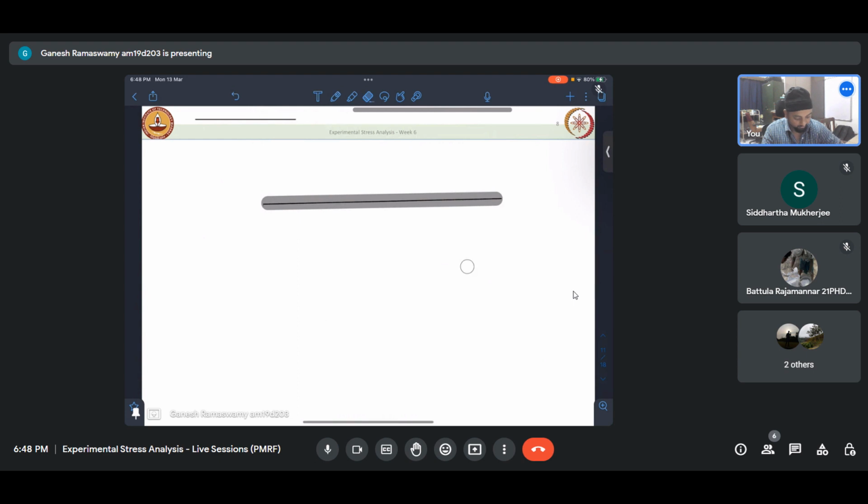So if my fringe order at that point is 1, then the fringe order at a pixel here would be some 1.1, let us say. And if it is increasing that way, then this will be, let us say, 0.9. Let the fringe gradient be from top to bottom. Now, if I were to have a pocket of pixels which basically has an if-else statement, what this is doing is we are having a mask like that. So this is my pixel mask.